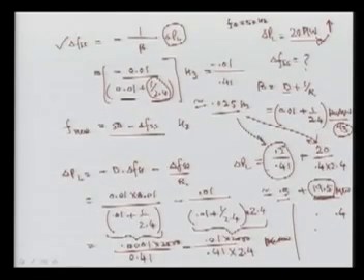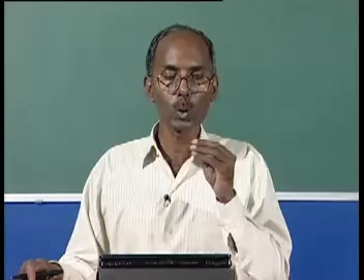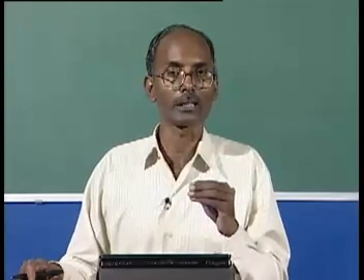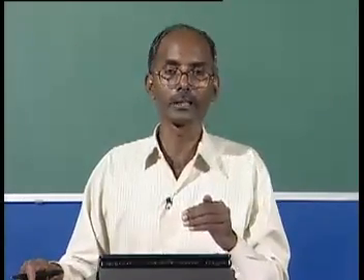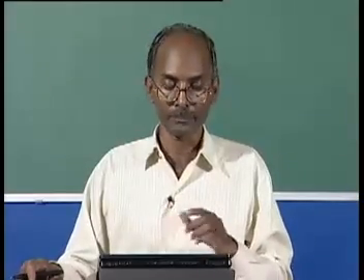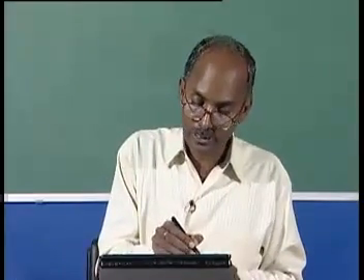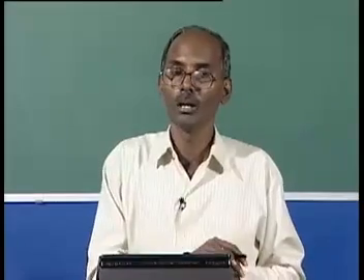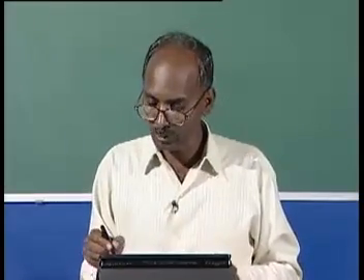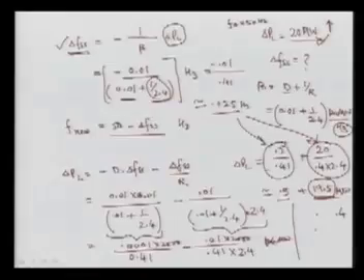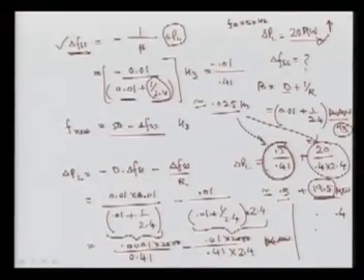One thing we can also see: when the load is changed, the governor is acting, and your net load release is there, but still your frequency error is persisting. The governor is supplying the load, and whatever the 20 megawatt has increased has been supplied, but the steady state frequency has still dropped to a different value.